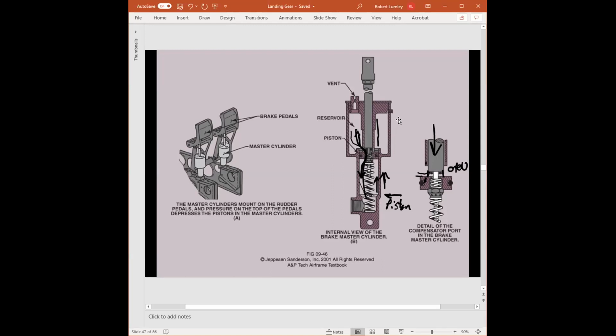Well, okay. Cars today, after 1967, have what's known as a dual bowl master cylinder. If you ever put brake fluid in your car, well, actually nowadays you have a separate brake fluid reservoir, but the master cylinder on older cars would have two bowls but one cap.